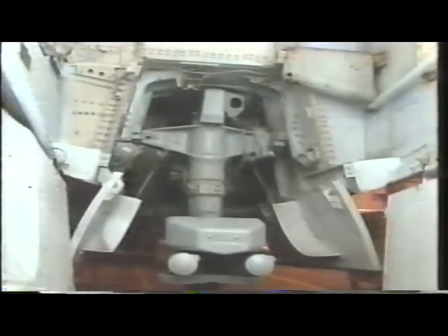The key to preventing corrosion on landing gear is frequent cleaning and lubrication of components. Refer to Figure 4-3 in your AC 43-4A to view the landing gear and wheel corrosion points in detail.